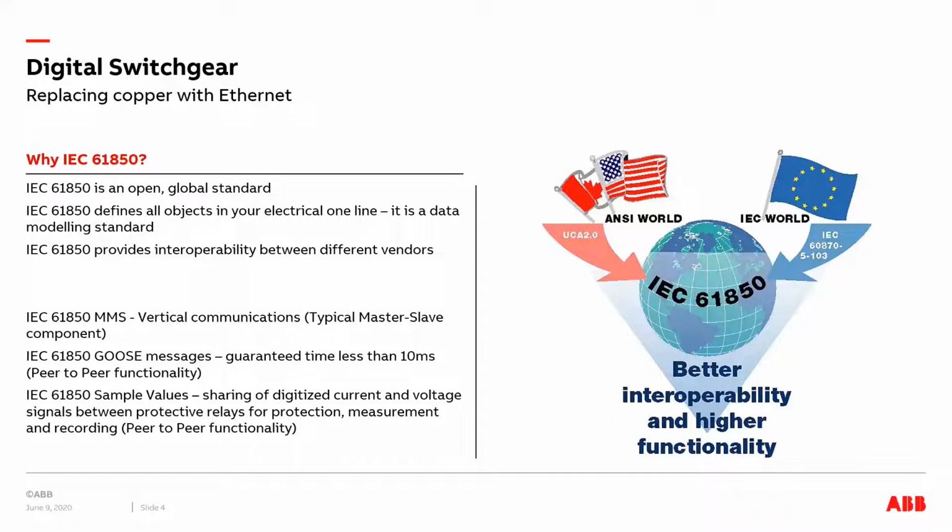IEC 61850 is a very broad standard, and a big part of it is communication. The different aspects of communication which enable digitization of the switchgear are mentioned here in the second half. One of them is called IEC 61850 MMS. It is the Manufacturing Messaging Specification, which facilitates vertical communication. So typically master-slave communication, where the devices talk to the upper level, a gateway or a SCADA and so on. And then the other part of it is called GOOSE messaging.